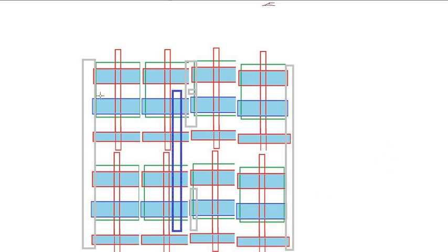So what's happening here is I am running the same metal. I'm drawing a cut layer over here so that this signal doesn't go over here. This is a separate signal. Now keep in mind, the moment I draw a cut, you will end up having different signals. You can treat this side as a separate signal, this side as a separate signal. If I don't draw a cut layer, it will create a short between two different signals. Okay, you will get a highlighting mark over here in the layout.